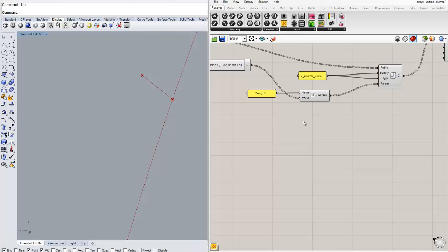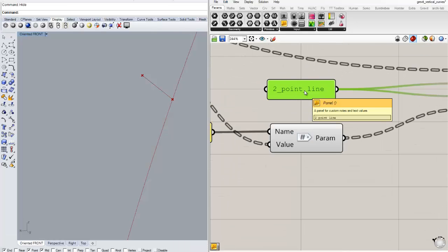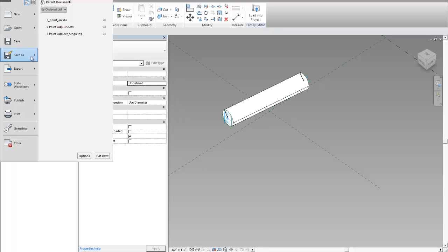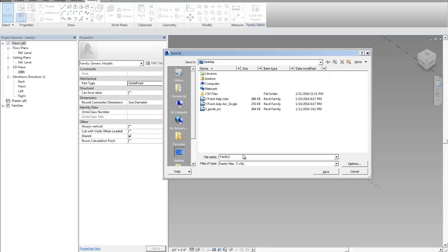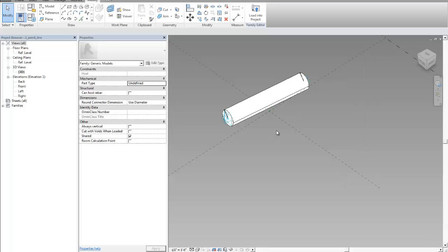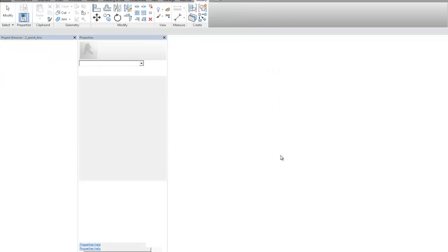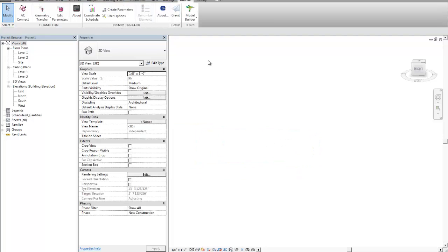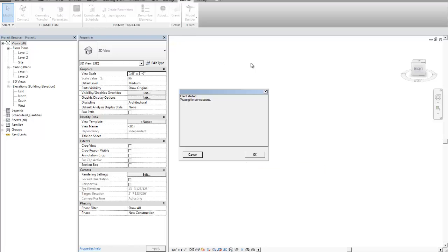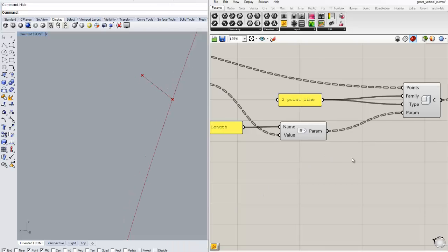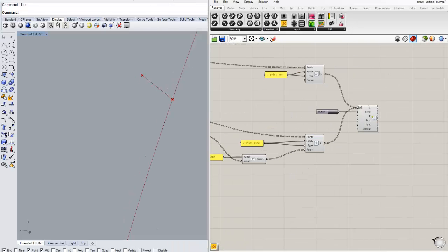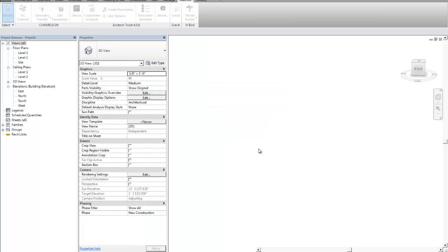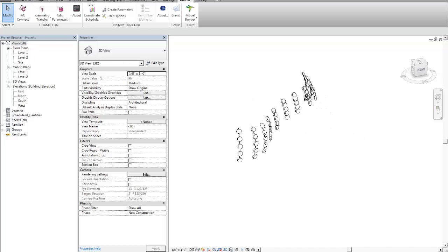And let's go back to Grasshopper again. Let's copy that to make sure that we save it under the right name. Then again, I'm just going to drop it on the desktop, give this the proper name, load it into the project. You don't have to place it. So once we're here, we have it loaded. Hit the Grevit button, go back here, hit this one, go back to Revit, let it spin for a little bit, and here we are.